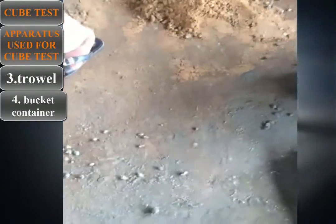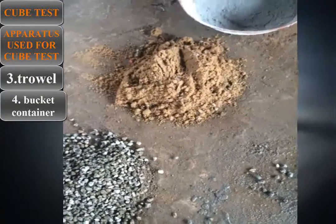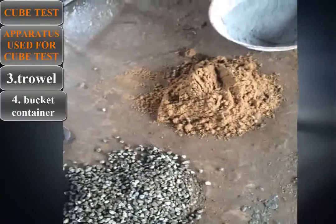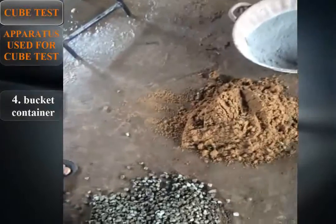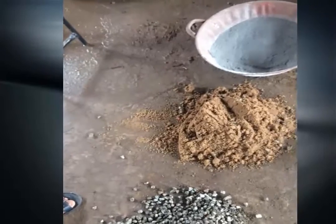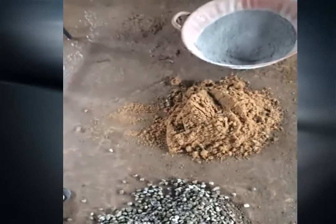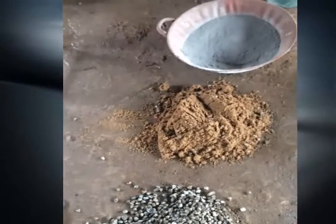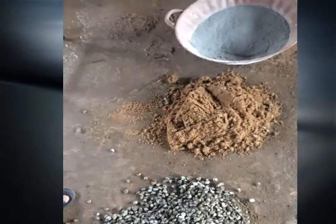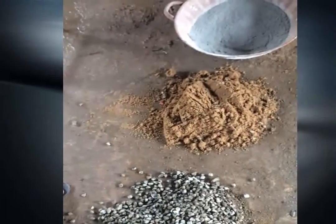Cube molds are usually 150 millimeter by 150 millimeter by 150 millimeter, or 100 millimeter by 100 millimeter by 100 millimeter, and can be made from steel or polyurethane material. The mold must be standard to specification. The mold must be lightly coated with mold oil before the concrete is poured into it to prevent the concrete from sticking to the mold and make it easier to remove the cube.